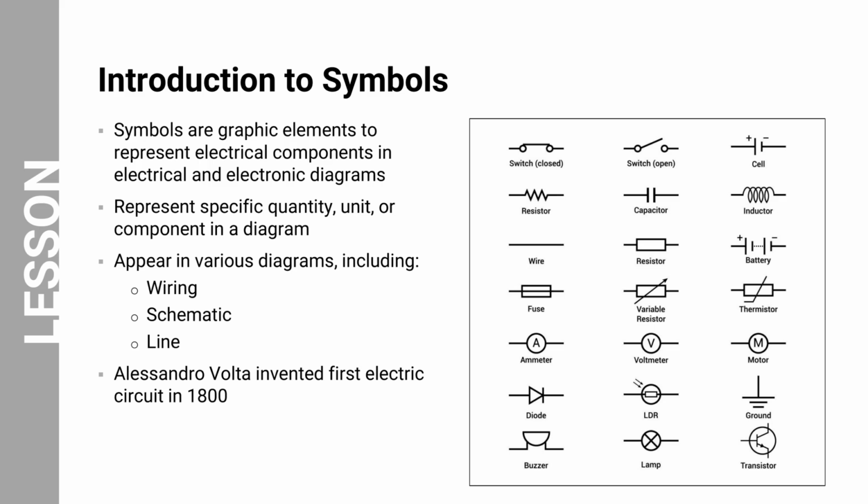General notes, such as abbreviations, legends, and symbols, are typically located on the first page of an electrical print package. Schedules provide details about light fixtures, equipment, and load specifications. These details assist technicians in understanding the components and their arrangement.